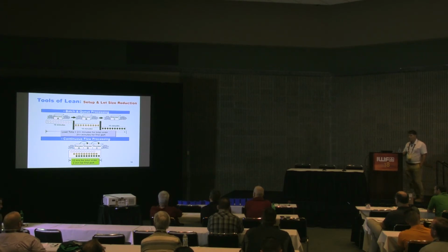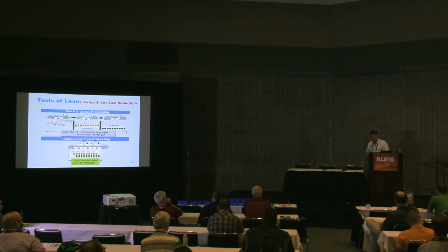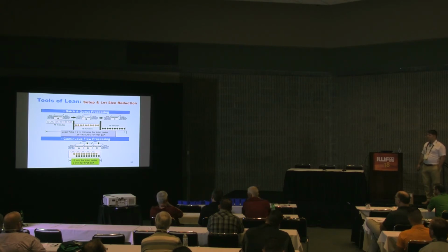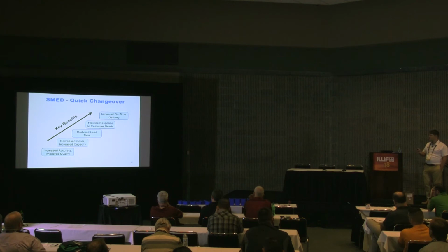And all this has to do with the fact that we batch because of machine setup times. I can't do that because I need to do another setup, so let me make a month's worth of parts, right? That makes more sense, right? Are we learning to see? Some of our habits are both beneficial and not beneficial. We create our own waste, sometimes for better or worse, right? So the lead time is significantly faster if you can get through all the 3 steps right away, instead of waiting for 99 other things to be done before process B begins, right?